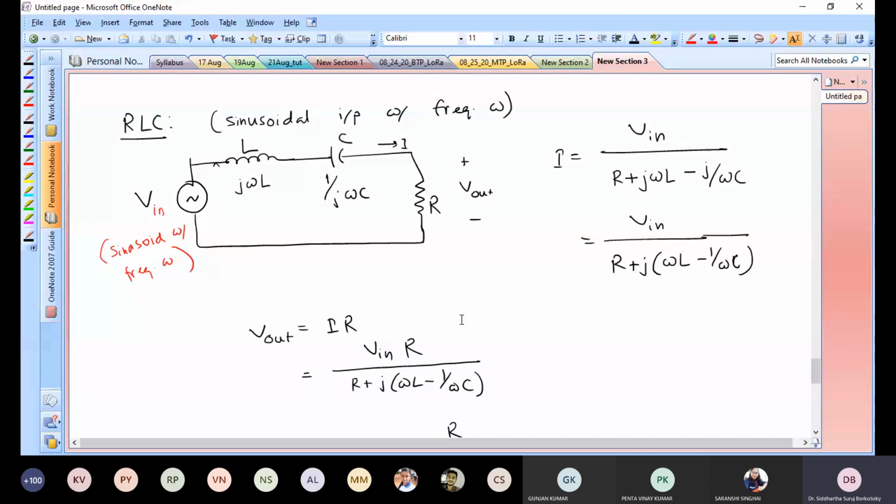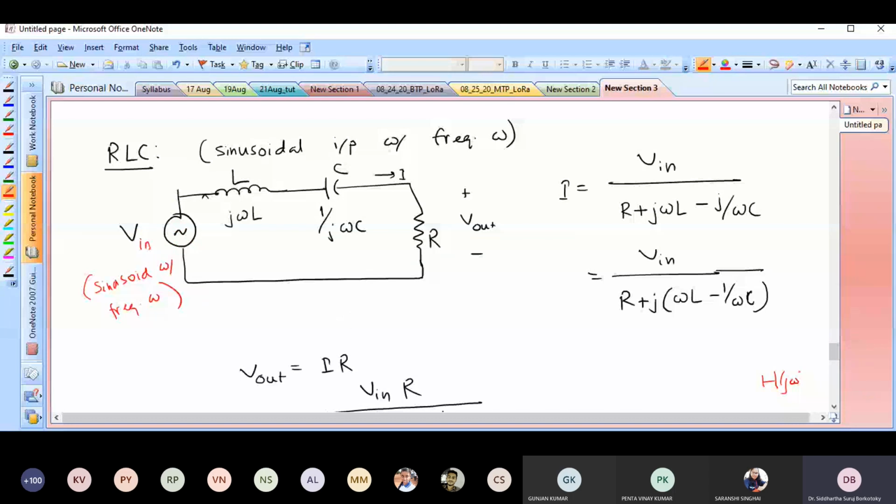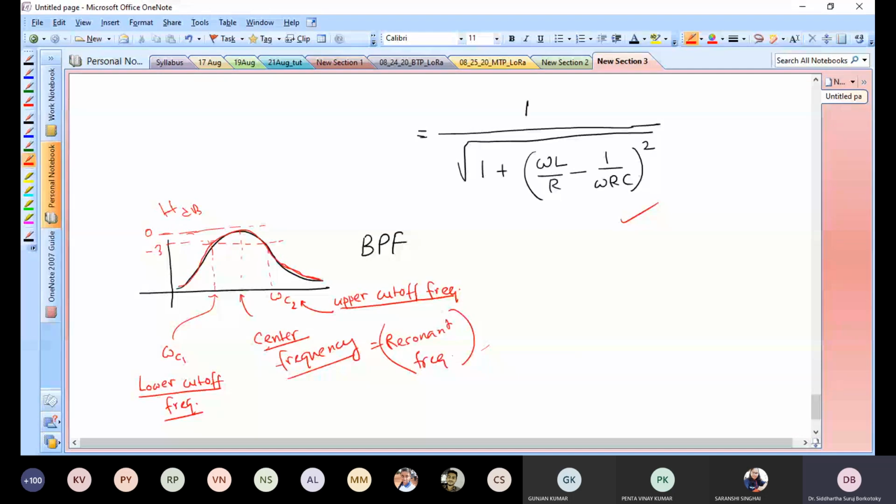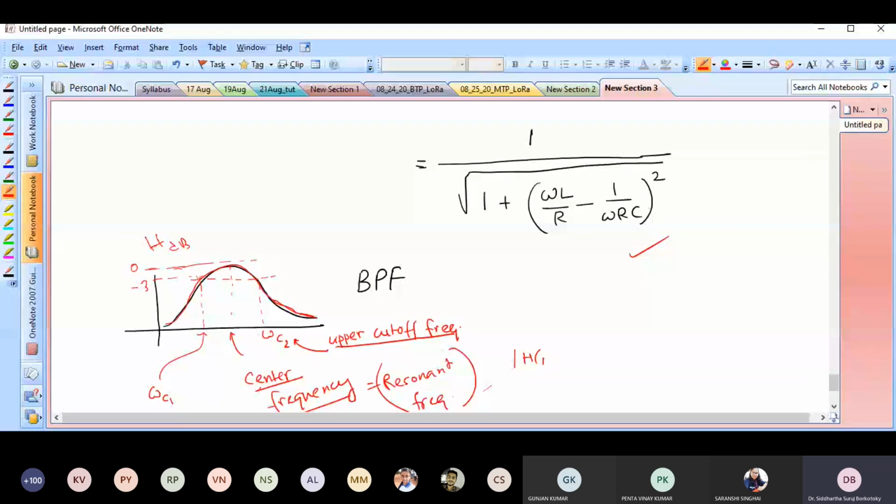And why do we add these things? They'll give us certain benefits. We will see that later. These are passive filters. One disadvantage of these filters is that they cannot do any amplification. As you have seen, in all these filters, the magnitude of H(jω) is less than or equal to 1.